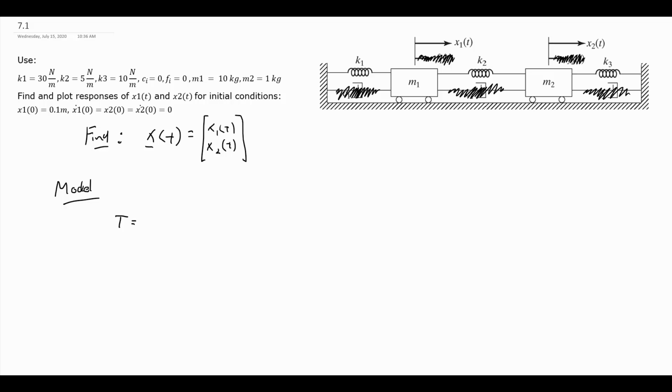So x1 and x2 are 2 independent degrees of freedom, and it takes knowing both of them to fully describe the system. And just because we know the value of x1 does not automatically mean we know the value of x2. Unlike the 1 degree of freedom systems where all of the coordinates were just scalar multiples of each other, these two are independent. And that is going to come into play in having multiple equations of motion that make our system up.